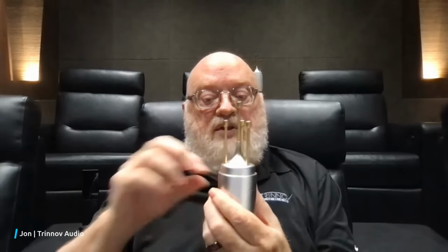The other big change is that unlike the V9 microphone that has a 9-volt battery in here for powering the four microphone preamps that are in the base, this is phantom powered from the CI. So A, your battery can never run out of power, and B, the CI has complete control over whether the mic is on or off because it just provides power when it's necessary to have the mic and gets rid of the power when it's not needed and could be potentially dangerous if you did the right combination of selecting the mic input and turning the mic on and not muting the system and suddenly you've created a feedback loop.